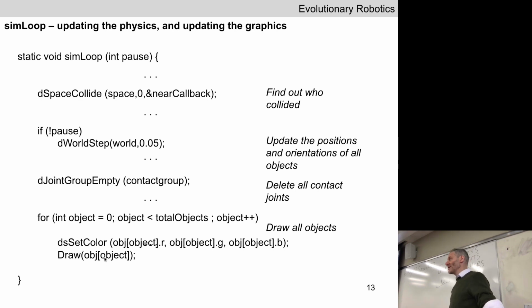One thing you can do, if you haven't done this already, is you can start to run your physical simulator in headless mode. Headless mode is slang for turn off all the graphics. Again, remember that there are multiple kinds of time unrolling in a physical simulation. There is simulation time, time 0, time 0.05 seconds, time 0.1 seconds, and so on. When you render the world, that's going to slow things down because your computer has to actually draw the graphics.